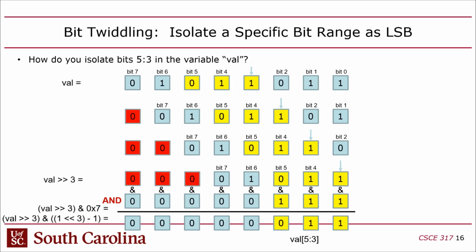Make sense? So multiple bits is, if you want to set n bits on in a register, you want to turn on n bits that are aligned on the right. You take a 1, shift left by the number of bits you want to turn on, and subtract 1. That's the way you do it right there. Let me say that if you want to shift it 4 instead of 3, that would be 16. 16 minus 1 is 15. That's 1111. That's 4 1 bits. So that'll get you what you want.